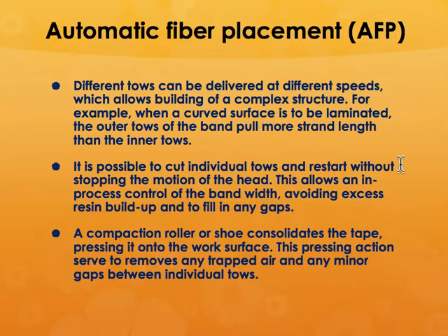The compaction roller will consolidate the tape and press it onto the work surface. You need a tool that is going to be holding it beneath, and this pressing action will make sure that there are no gaps or porosity or trapped air between the individual tows.